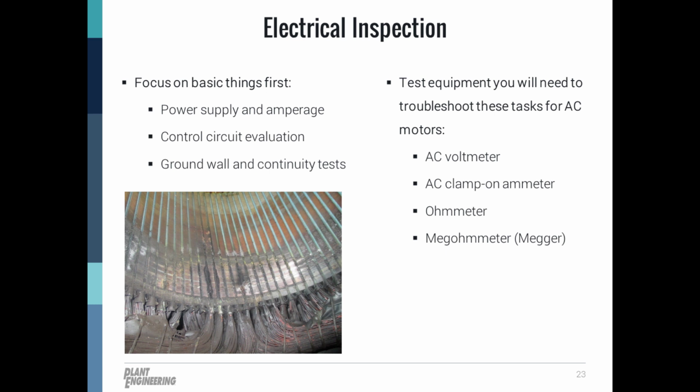So, another useful test to perform when troubleshooting the motor with an electrical fault is the ground wall and continuity test. But just make sure, if your motor is powered by a VFD or a soft starter, that you disconnect the motor leads from that device before beginning these tests.